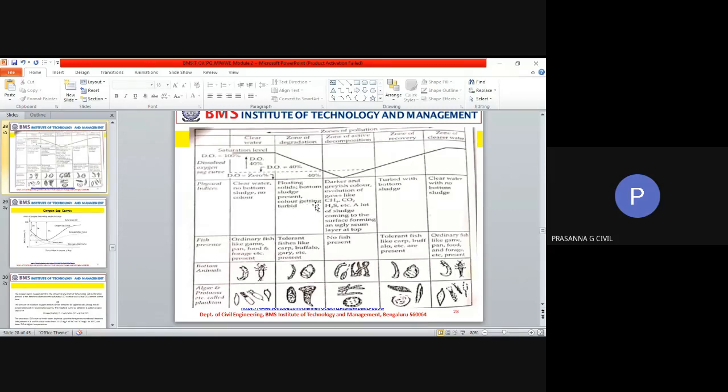When you pass from degradation to active decomposition stage, you will see that the water gets darker and grayish. That is because of the active decomposition that is happening. Okay, the change of color will be very predominant. You will have gases. And like I told you, please keep it in mind: whenever aerobic decomposition is there, we expect only 2 end products, carbon dioxide and water.